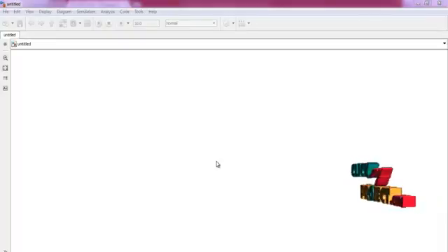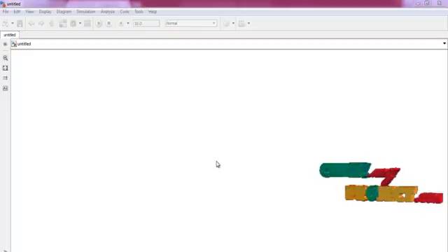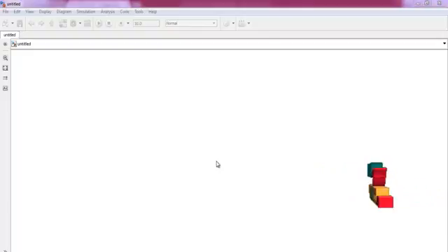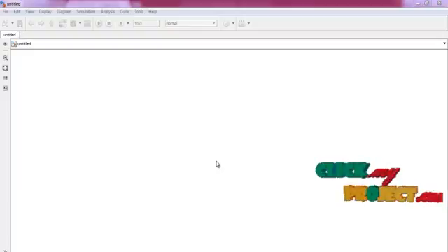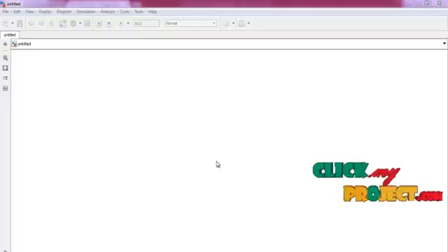Initially, three signals are given as input: one is a sine wave, another is a square wave, and the third is a sawtooth wave. We have to combine these three signals into a single signal and pass that signal into the RF signal generator. From the signal generator block, we get a single signal. That signal is given to the ADC block, where analog to digital conversion is performed.